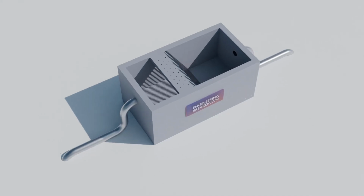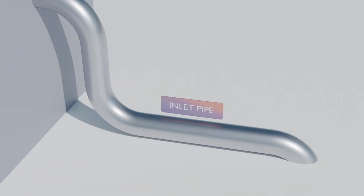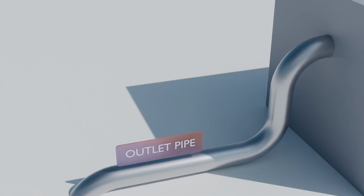A simple screening chamber typically consists of a concrete structure designed to remove large debris from incoming wastewater. It includes an inlet pipe that carries untreated water into the chamber, and an outlet pipe that conveys the screened water to the next stage of the treatment process.